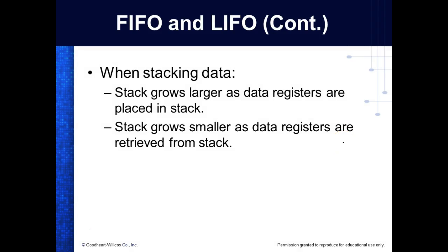When stacking data, stacks grow larger as data is stored on the stack. By the way, technically, when we put that on the stack, they call that a push. The instruction, but if you ever hear say, well, you need to push it on the stack, that's what they're talking about. And then when we take it off the stack, they technically refer to it as a pull, or they'll call it pop. Pop the stack. You need to pop the stack, which means do what? Pull the information off. But the instructions that we got, and as the stack grows smaller, the data registers are retrieved from the stack. You're not wiping the data out, you're just incrementing through it, right? So if you knew where the stack was, you can access that data just by using your other address in there.